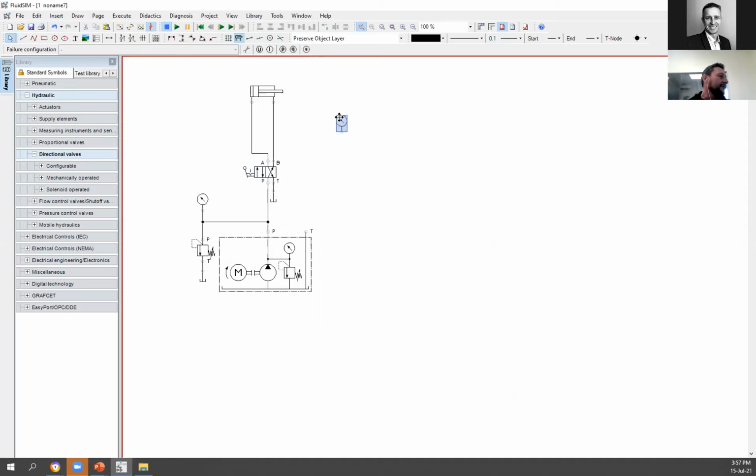Okay, what I want to do is we can just put a gauge here, somewhere, anywhere. Just remember the gauges you can put anywhere on the circuit, and you can have as many as you like. Okay, because it's just your eyes. Remember with pneumatics, it's easy. You unplug the pipe, you check, there's air there, and you can put a gauge on it, connect the gauge, and see what the pressure is while it's still in your hand. But with the hydraulics, you can't. What you can do is you can have some plug points at different points on the system, and you take your gauge and plug it into different points and check the pressure that way.